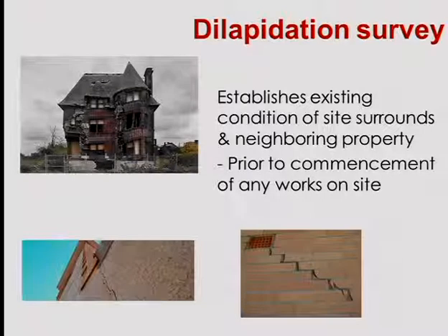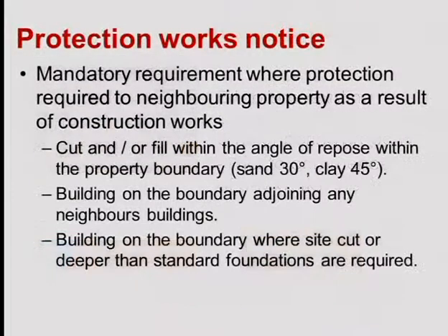So you'll see these cracks, someone will claim that you caused that problem and it becomes a real issue. So when you identify those problems, part of your site analysis says, well, I need to protect that building so it doesn't get worse. I need to make sure that I don't create problems, so I need to create some protection works.